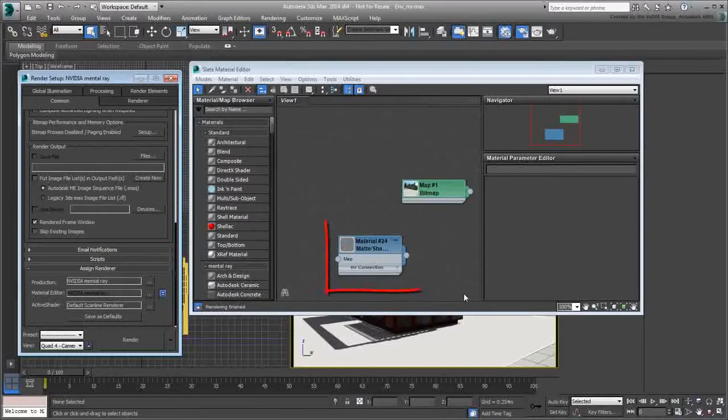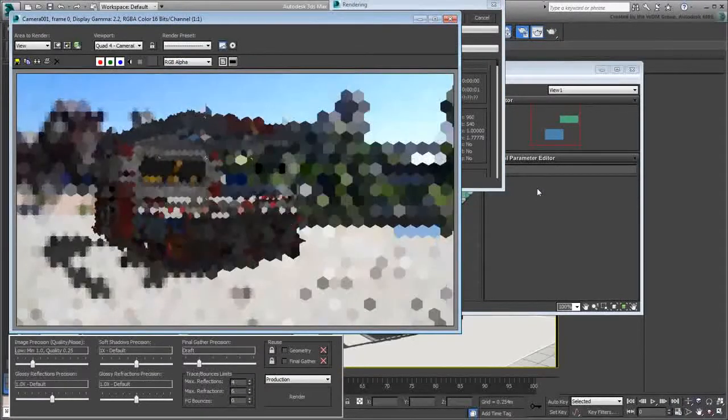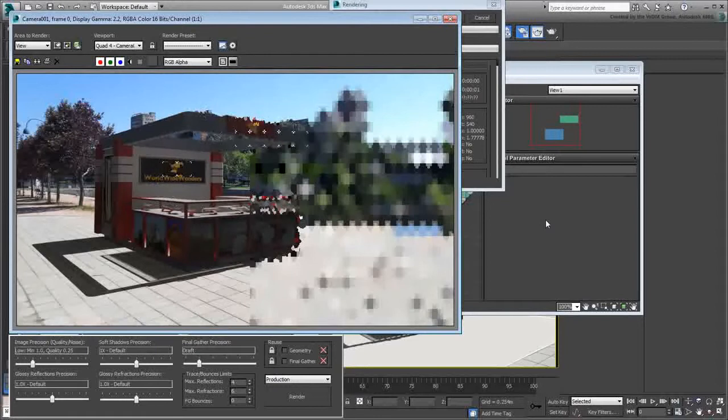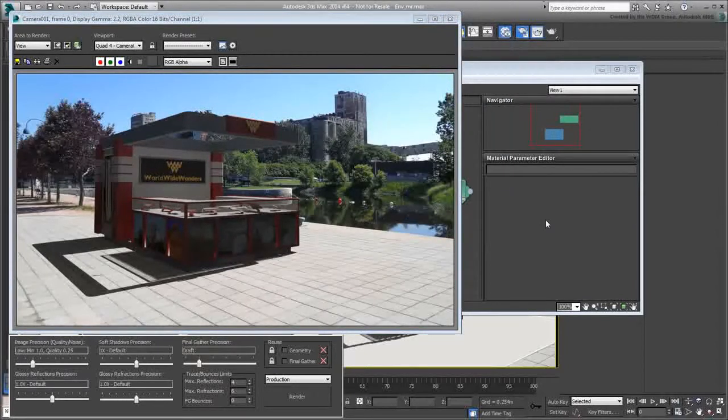The existing matte shadow material node, however, is still in the viewer. Try to render the camera view, and you will see that it's still collecting shadows as it should. This is why I mentioned that it's pseudo-compatible, even though you want to use a similar yet different material when using mental ray. You'll get to that in a moment. First, you need to adjust the lighting.